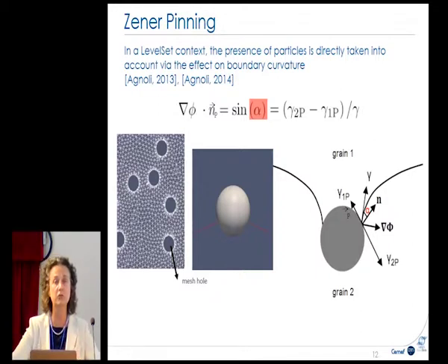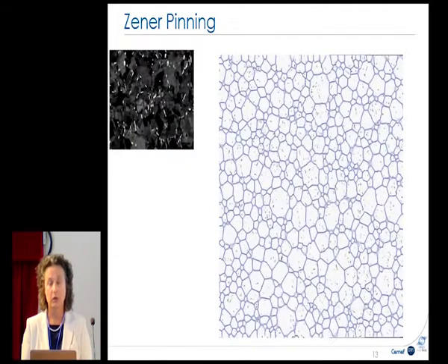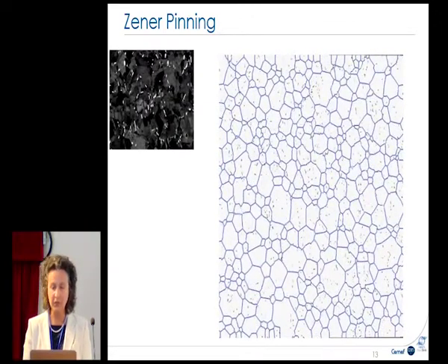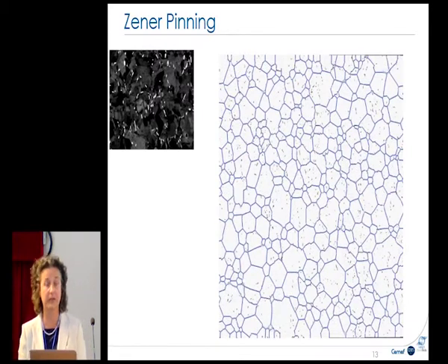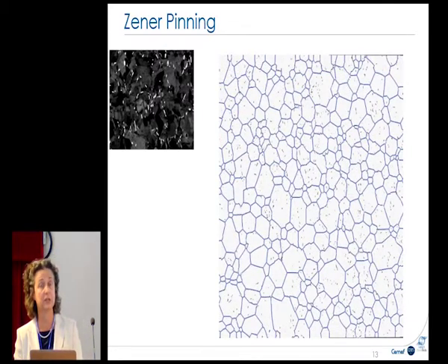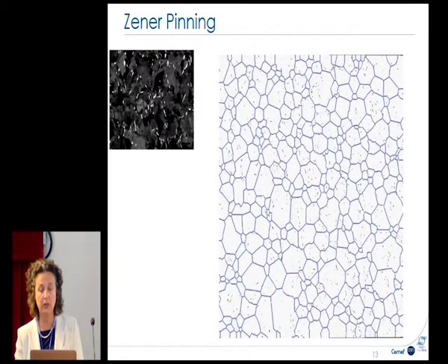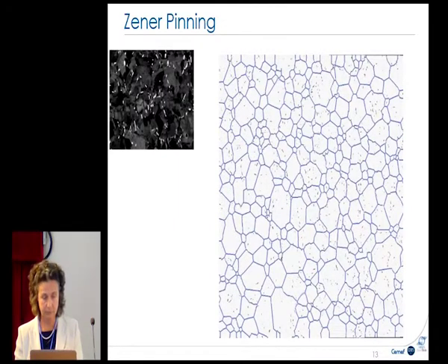It is the equation that permits the grain to grow or to avoid some obstacle and so on. This term is the linear dislocation energy. Here is the dislocation density, here the grain boundary energy, and here the grain boundary curvature.